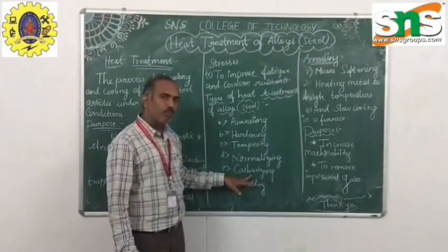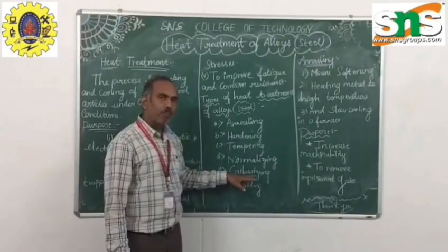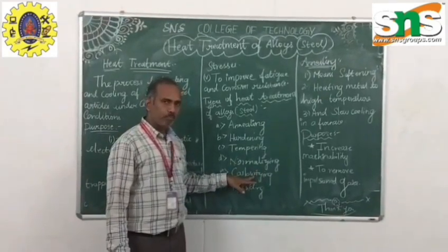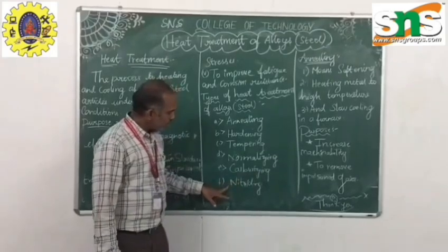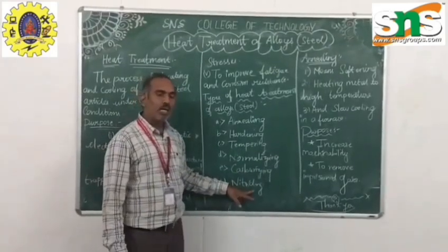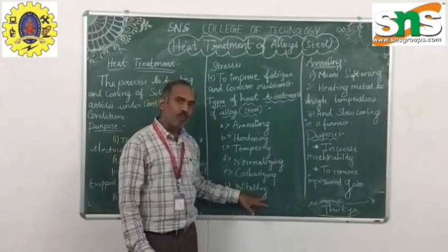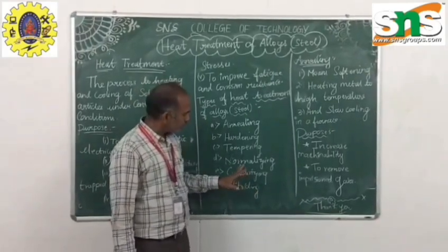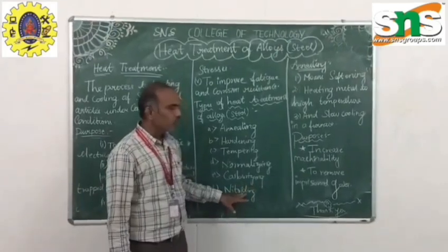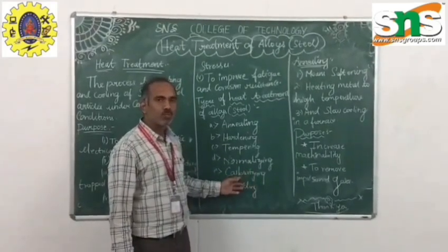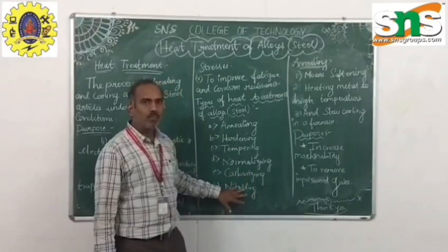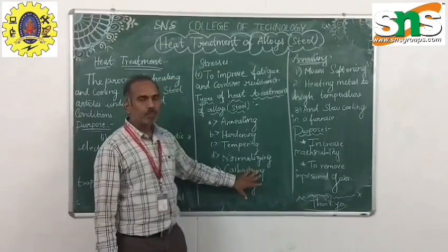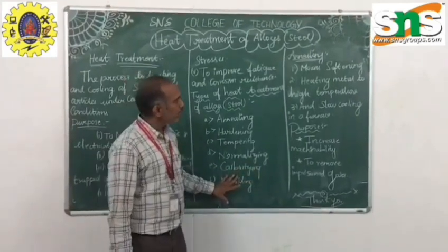We can modify the surface area with carbon material. And the sixth one, nitriding, uses nitrogen, so the surface is modified by nitrogen. We can choose different sources of carbon and nitrogen for carburizing or nitriding. Accordingly, we can get different properties of the steel material.